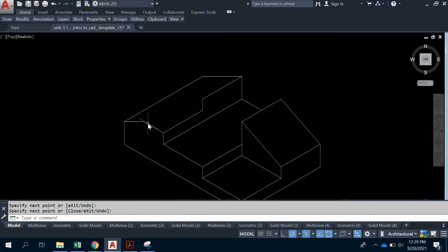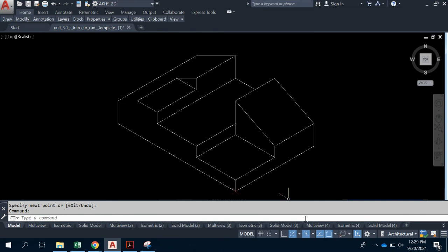Okay, now all we're missing is this right here for now. So we're going to do a line from here up and to the right 1, enter, should come down and to the right 0.5 here, should snap into place, and then the last thing is this corner right there. Now all you're missing are the 2 ellipses, one of them right here.